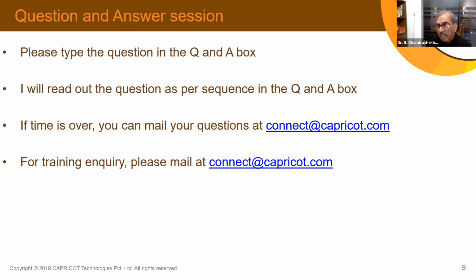So whether it is air conditioning, water, or your disposal, that is stormwater as well as your sewerage, all play a vital role, and you have to start thinking about them from day one. The first question should be, when you visit a site, where is the source of electricity? Where is the source of disposal? Where is the source of supply for my water? After that, you can start thinking about utilizing your contours and your site layout.